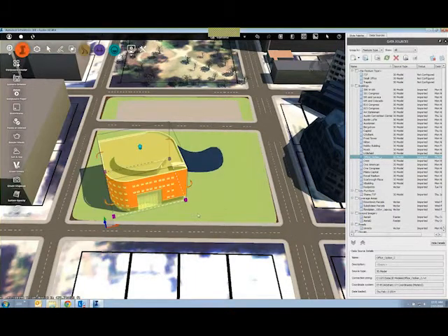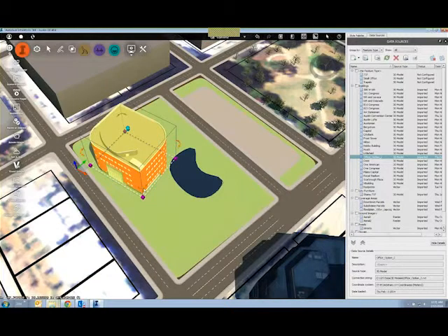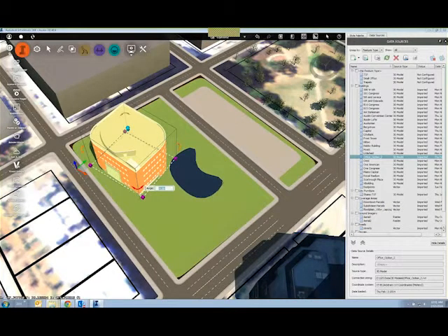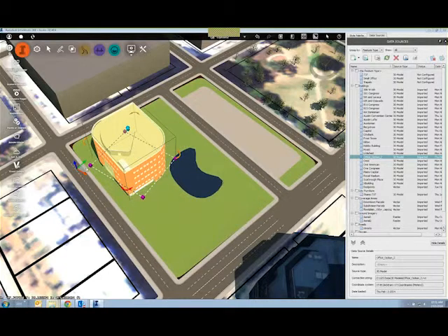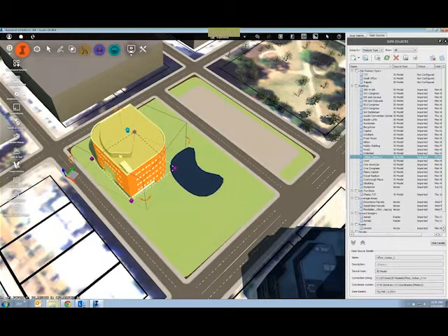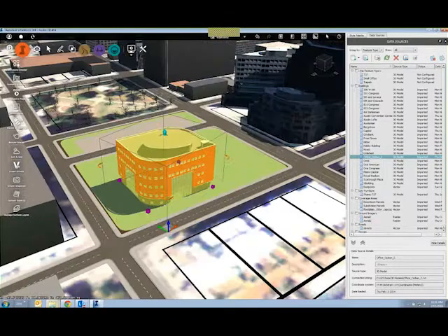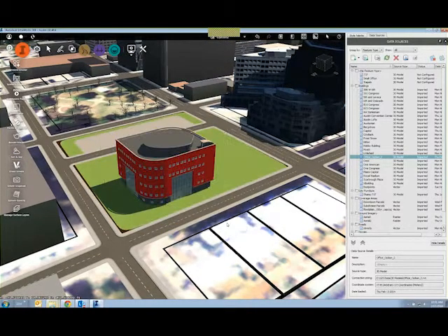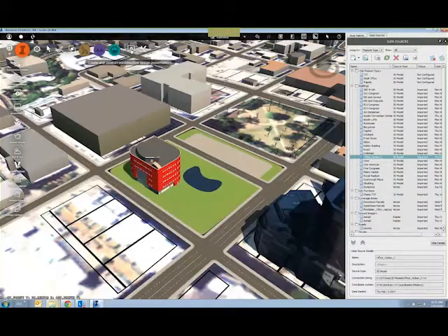And now I start taking this model and I want to present this model perhaps. I'm going to use some very simple tools in InfraWorks to create presentations. We've got what's called a storyboard, and the storyboard allows me to create simple, easy animations. Now I'm going to do it based simply on a camera path animation. I'm going to start out just a little further away, maybe over the town lake area.